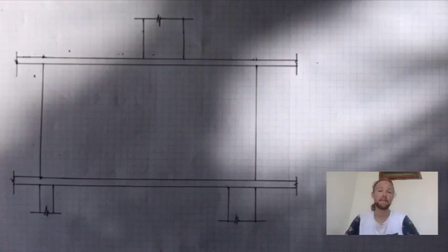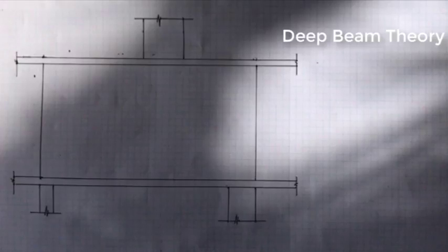So the strut and tie method is best for a lower span to depth ratio. If we get a higher span to depth ratio, we can probably start looking at the deep beam method. So there's two ways of solving this problem: one is strut and tie, the other is the deep beam method. If you design this as a deep beam, you use the same process as simple beam theory to calculate the maximum bending moment at the centroid and shear forces at the edges. One way of doing this is using the CEB method, which can be found in most textbooks and is covered in university.